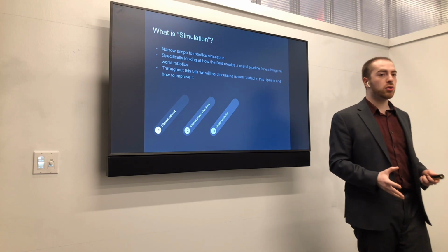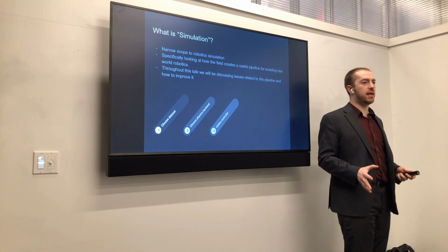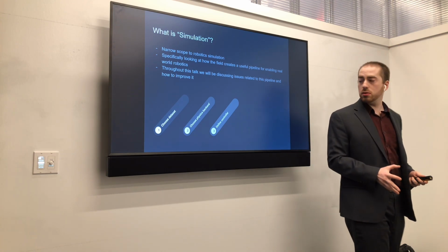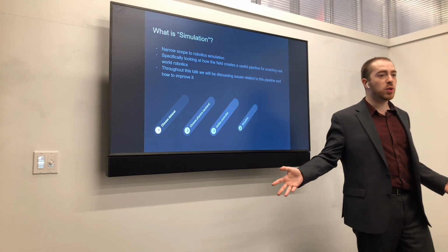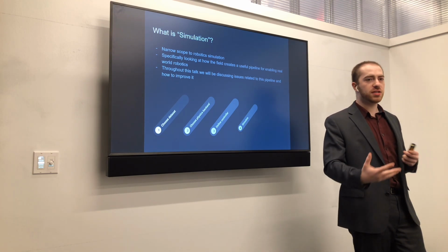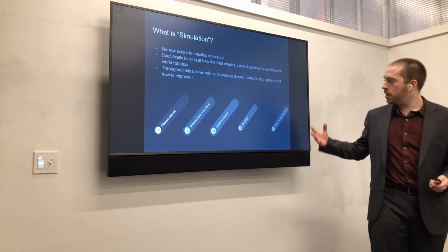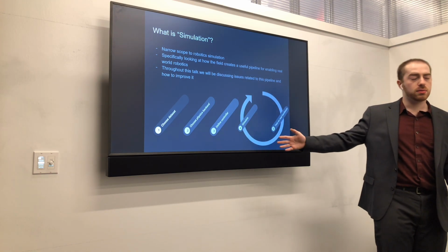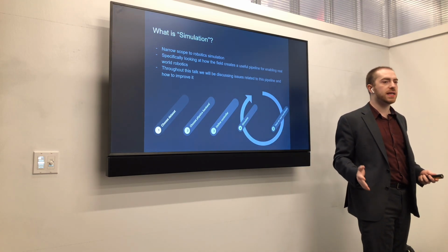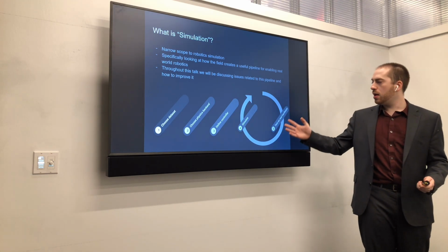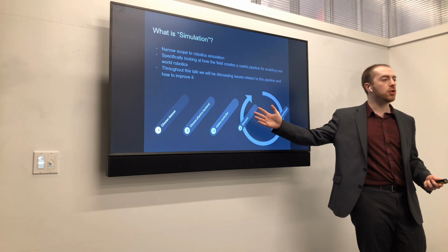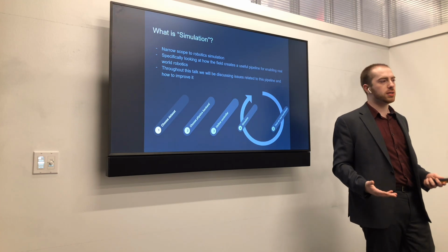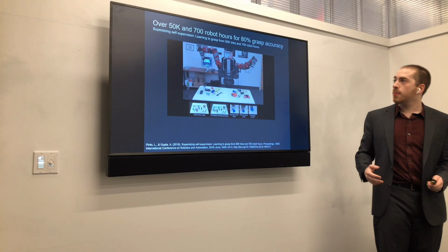Then you want to define the controller that actually dictates the behavior of the agent in the simulated environment that also translates onto the real-world environment. Then obviously you simulate what you're trying to test, have some metric to evaluate how it's performing, test it on real hardware or in a real environment. And this simulate-test-on-real-hardware becomes an iterative process where you evaluate, it dictates how you update your simulation, dictates how you update testing on the real hardware, until you converge on a solution to your particular problem.